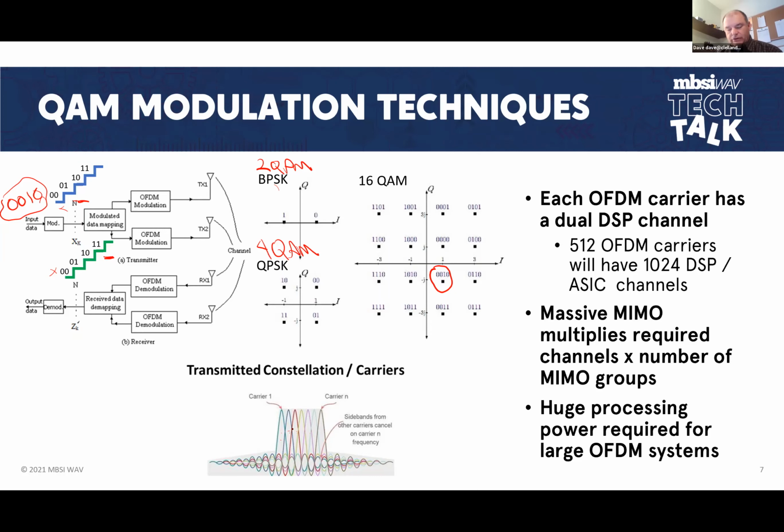If I'm doing a 512 carrier OFDM like the 450s, for example, then I have some number, 436 or some number of these stages in the ASIC that I need to process data at the same time so that this is transmitted simultaneously. These OFDM carriers are transmitted all at the same time. They're not transmitted sequentially. So I'm not using one circuit to generate all of these carriers. I'm doing it simultaneously.